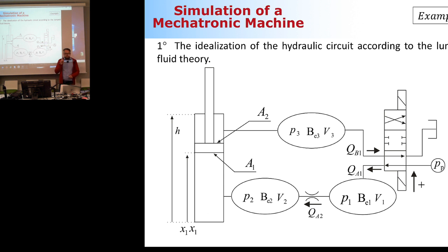All right, step number one is a drawing that shows how you can discretize your hydraulic circuit, and what you are assuming the positive flow rate direction to be. You can do this discretization by comparing the pressures in the locations where you are assuming pressure to be equally distributed. For flow rate, the positive direction can be anything you want. But once you make your decision, you must be consistent. You cannot change this after that.